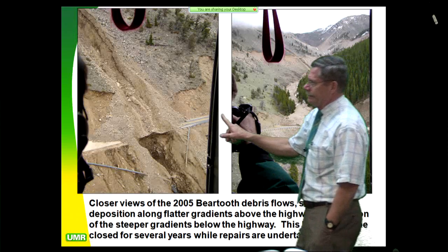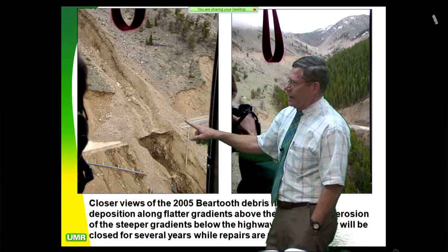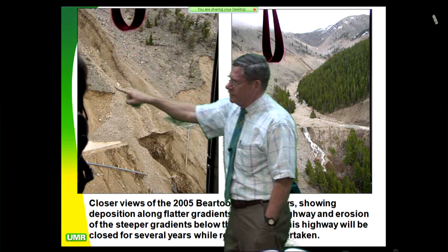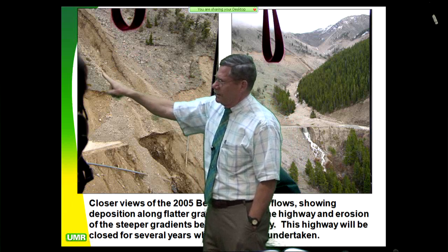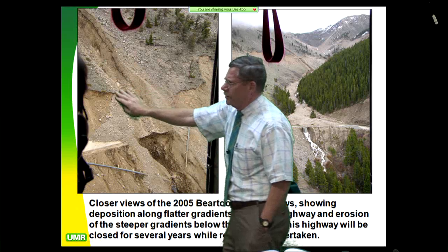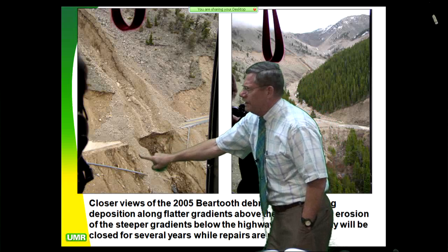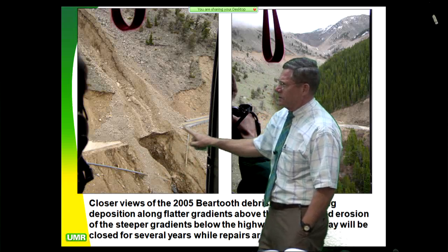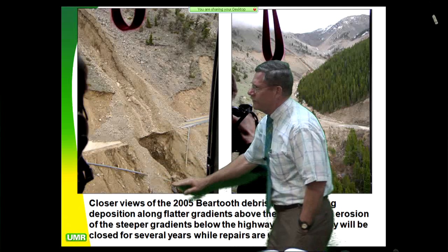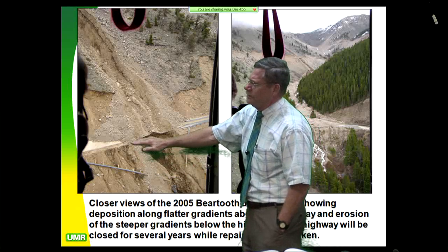This is a 2-lane, high-speed highway, and it is just gone. Now, that might look easy to fix, but it isn't. This is a scree slope. Talus fan, it's got a channel about 80 feet deep that's been gouged out by the debris flow. The road's gone, and where the road was is completely undercut here because the road paving surface becomes a weir of sorts. So the road is completely gone underneath. You have to come in here with mechanically stabilized embankment, geogrids, and rebuild this whole thing.